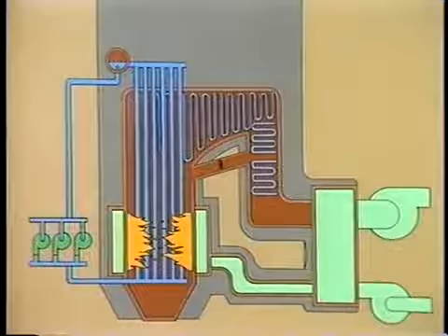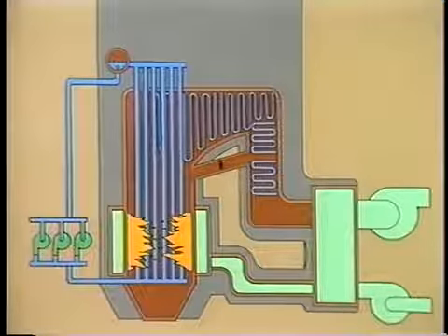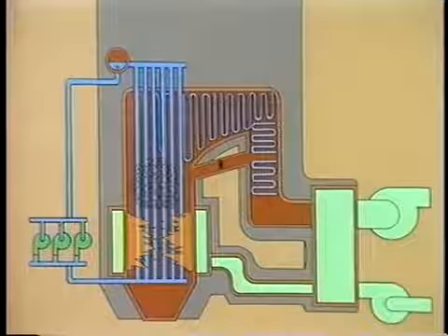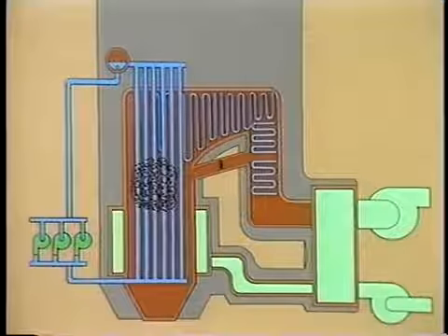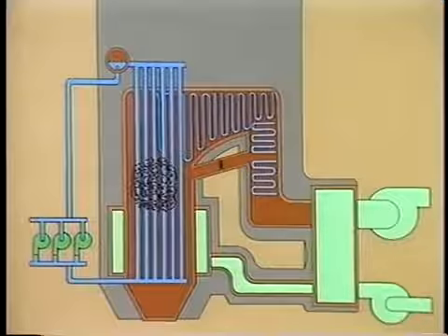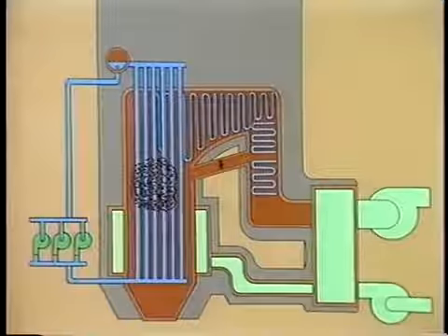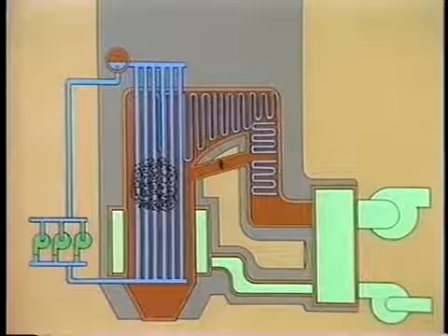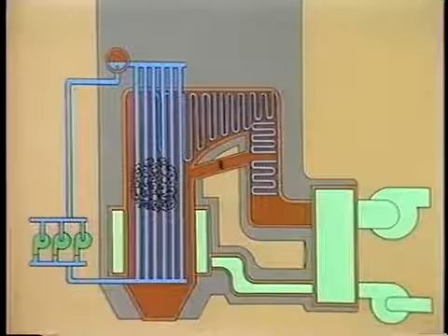Finally, since the boiler explosions which have occurred in the past have often been fostered by a loss of boiler flame, knowing the procedures for dealing with this situation and the proper procedures for purging your boiler will prevent boiler explosions. In the next part of this program, we'll look at some situations that can lead to the loss of a boiler flame and the typical procedures for returning the boiler to normal operation.